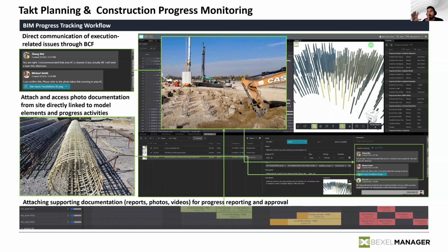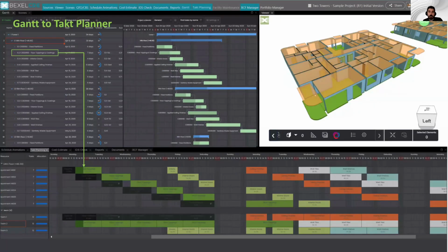We created an issue. We selected the future possible affected foundations. When I have to do these foundations, I'm simply going to select them from the schedule. I'm going to filter out the active issues and see if those issues were solved or not. If they're not solved, I'm going to reschedule my work and probably jump to another area. So at every moment, I know exactly what is expected from me and what the conditions on site are.